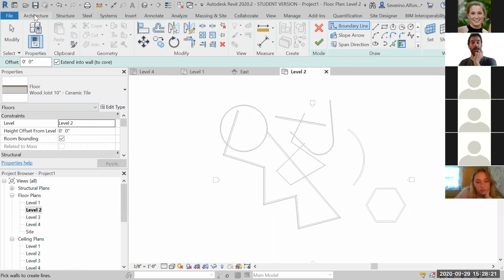As I clicked floor, we jumped to the modifier, remember? There are slightly different things happening between walls, windows, and three-dimensional components and more orthogonal components like floors, ceilings, and, as we'll see, roofs. When you go to floor, ceilings, and roofs, you get this little mode, red X, green check. While you're in this phase, this means that, hey, create your floor and click on I'm done, check.